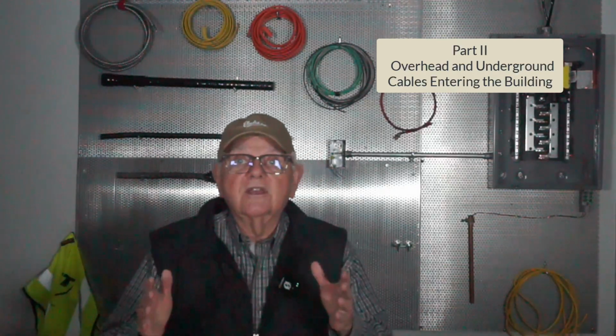Okay? 770.47 is rules for underground fiber. And so if we're running with light and power cables, the general rule is we've got to have a certain amount of separation. And we may need a physical barrier in there, most likely. So that's going to be specified by 770.47, and it's going to give you some ideas on what you can use. So I have to have a physical barrier to separate the two systems, and my direct burial fiber must always be separated by at least 12 inches from the light and power cables. But when I come into that manhole, if I'm coming in with both light and power and my fiber optics, I've got to put my barrier in there.